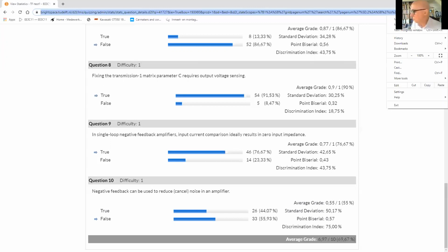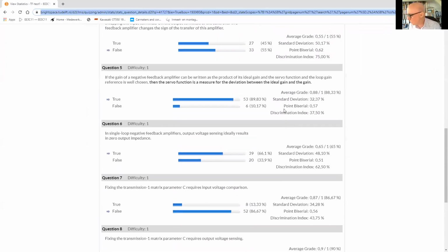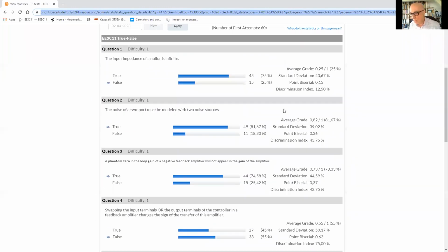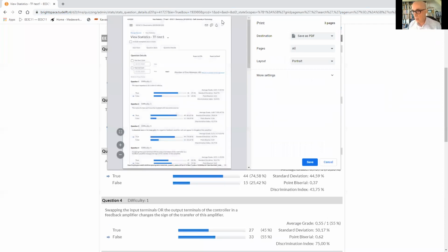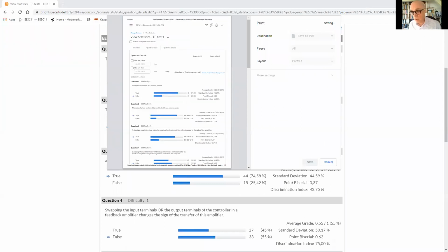So in section 7.5.2, there are these noise transformations done for an example for a passive feedback voltage amplifier, and the starting point of your design is that you draw uncorrelated noise sources. Now, if you then split a current source or move a voltage source through a node, you get two correlated sources. And in the example, you see exactly how we deal with it, because then plus and minus signs become relevant because the two sources are correlated and they can even cancel. It is not that physically you are canceling noise.